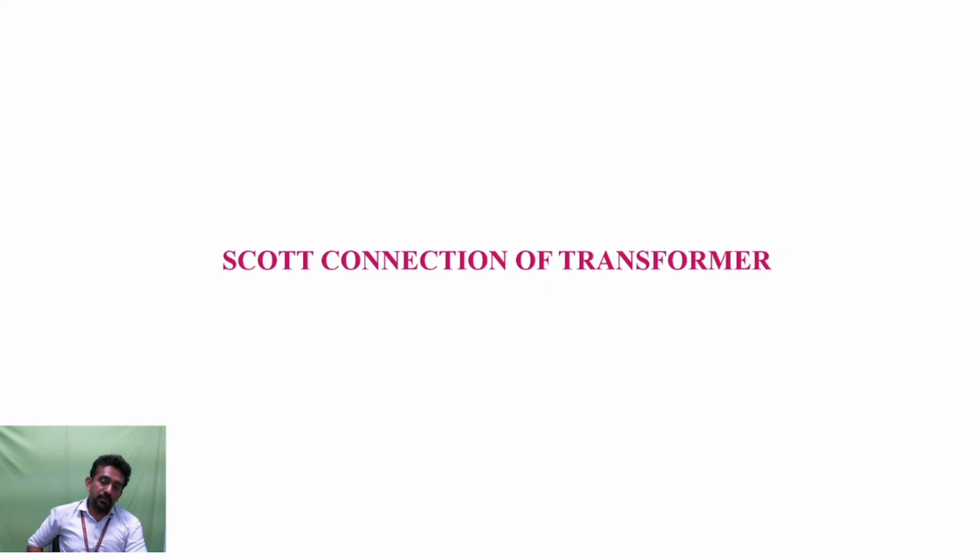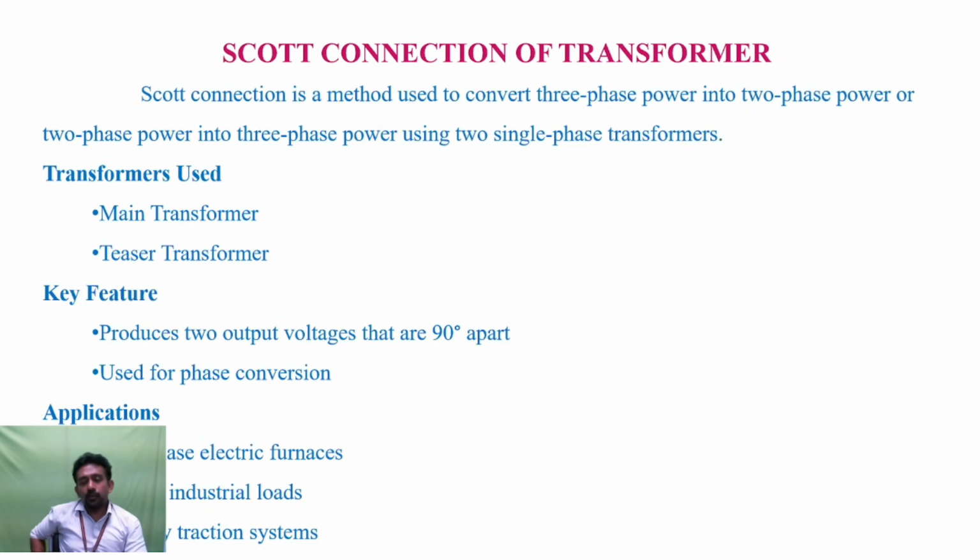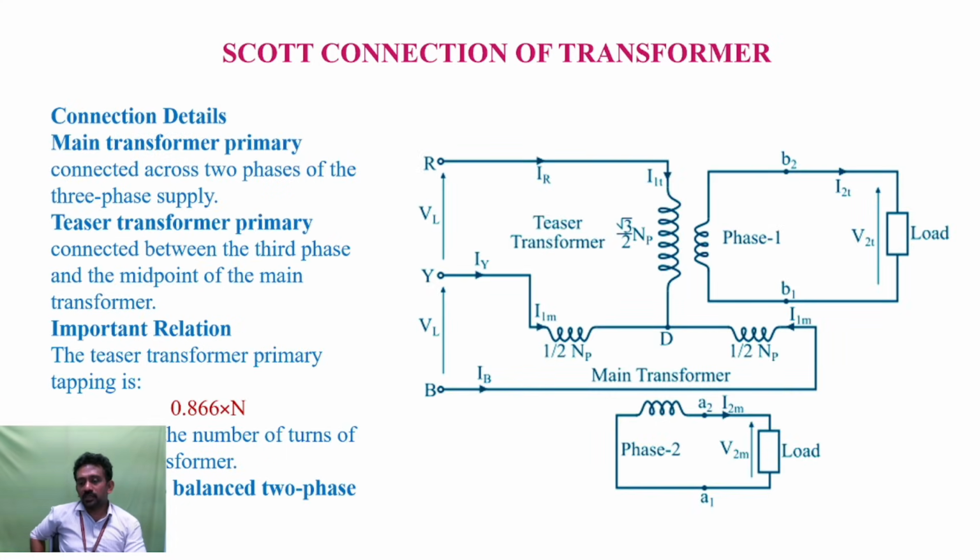And the Scott connection of transformers is another important topic, wherever we require a two phase power supply. By using two single phase transformers, we extract a two-phase power supply. Here the transformers used are a main transformer and a teaser transformer. This is the Scott connection of transformers.